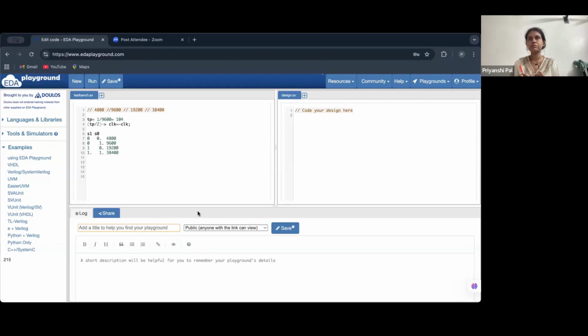Then the master again sends the slave address and register address, and in return the LCD display sends an acknowledgement to the master, and like that the display receives the data from the master and displays it on the screen. So here I have one master and two slaves which are communicating using the I2C protocol.